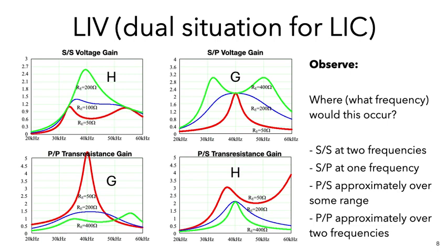Whereas for SP compensation, for this particular case, we have this point identified as the LIV condition, load independent voltage condition, at this particular operating point, and also the optimal efficiency point as well.